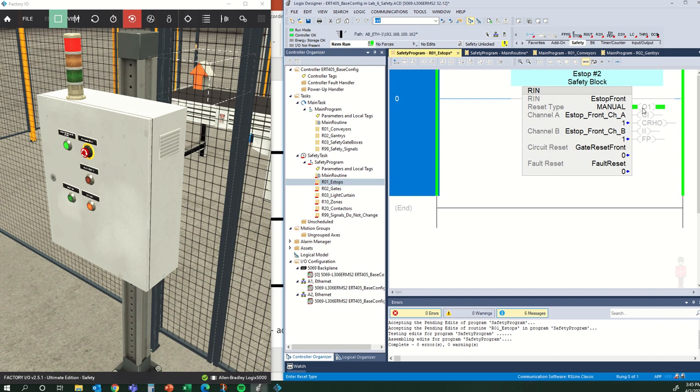It has the 01 tag on. If we push the e-stop button, that disappears. You can see these inputs went from 1 to 0. If I pull this e-stop back out, the inputs come back on, but I don't get my output. I don't get the output until I actually reset that. And that's the difference between manual reset and automatic reset.